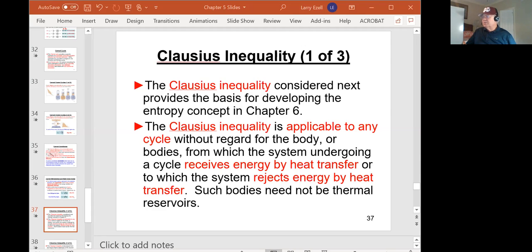Let's look at the heat pump cycle. Again, I'm leaving the outside here and the inside here, but now what you want to do is heat the inside. So you're taking heat from a cold area and transferring it to a hot area. And again, you're going against the second law, but to do that you have to have this compressor. Like I explained, the heat pump and the air conditioning system are identical, except you reverse the flow of the refrigerant.